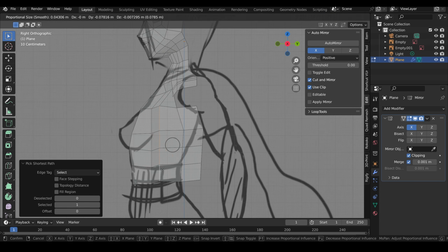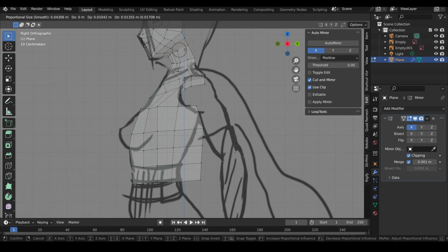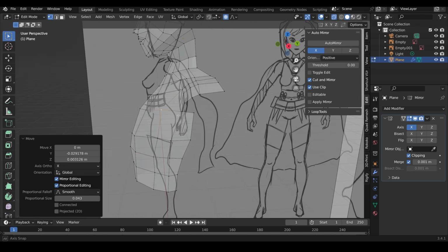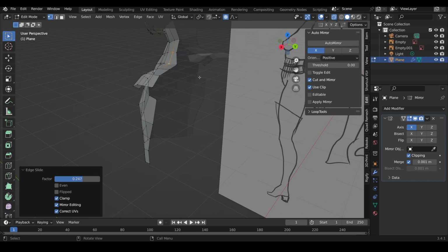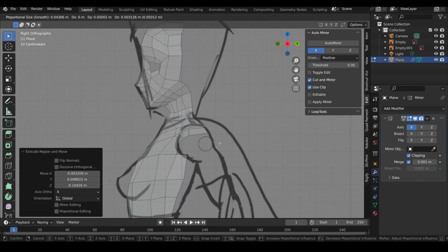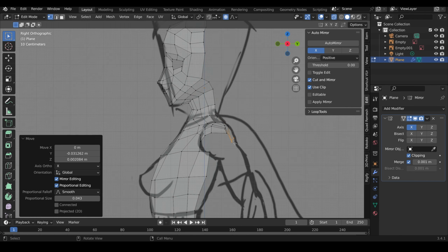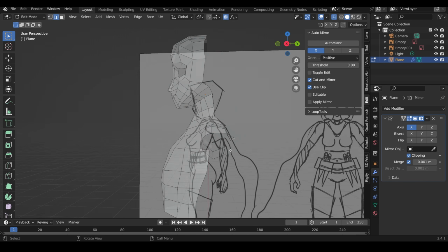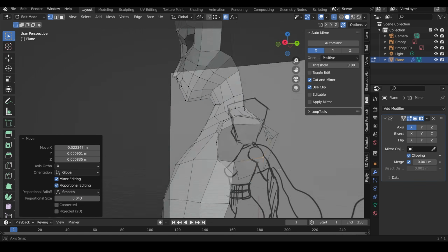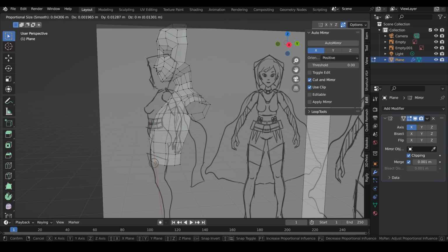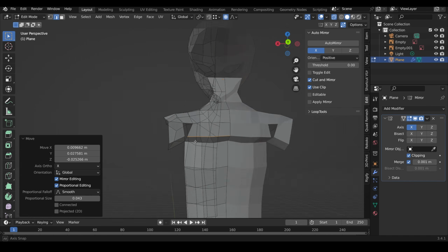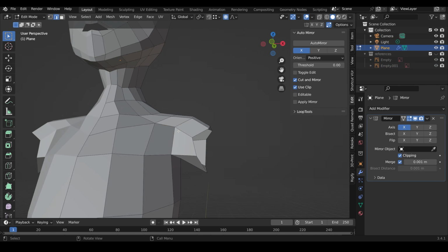I often see beginners make very flat, square type shapes, but it should be very curved. It's probably because lots of beginners use a cube and then build it from there, and then it ends up looking very cubic. You can see me filling in the back of the body here that I'll extrude the cloak out from. And I always like to model the arm socket, so put in a cylinder almost. Then I know I've got the right count that I want for the arm in terms of the amount of faces going around, and I can just attach it up to the body afterwards.